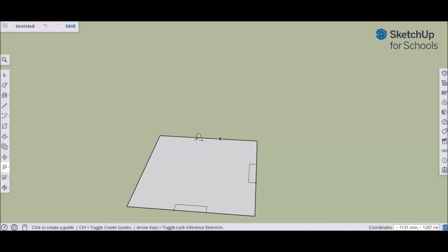Click in, find that notch, so you can see it says guide point. Bring my rectangle out 5 millimeters, and the last one, near the end, 30 millimeters down. Yep, click, rectangle, and there we go, 20, 5. Now I've got my base, which has got the joints lined up.